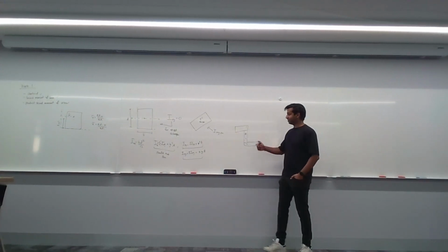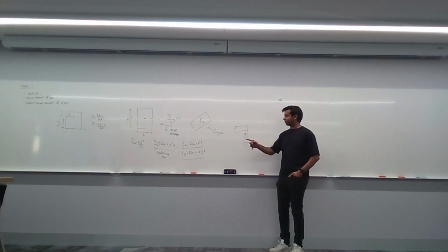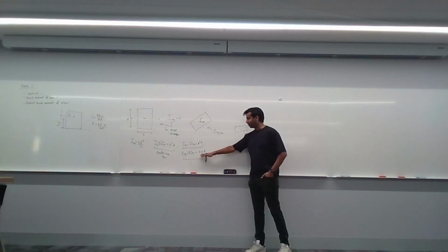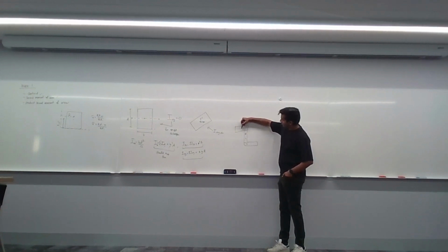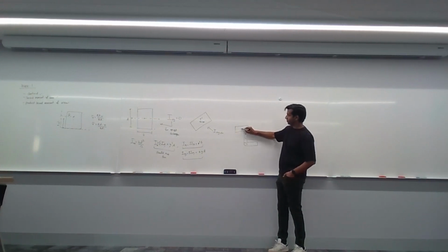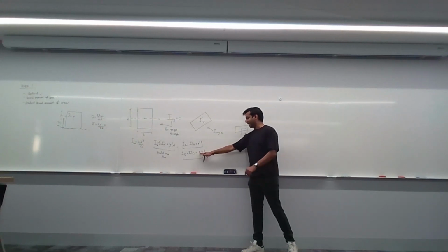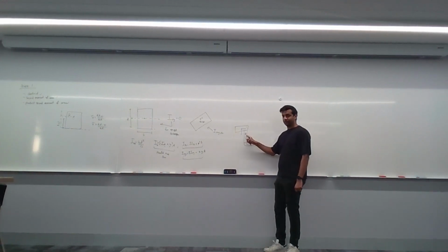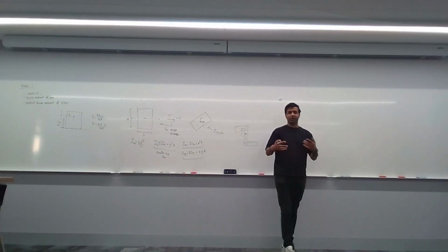Then we chuck this formula in to calculate the Ixy for the entire shape. So how would we do that? We first need to ask, what's the Ixy for all of the individual shapes? Because these are all upright triangles, it's all 0. So Ixy is 0, 0, and 0 here, so this entire term goes to 0. Now I want to calculate what xyA is for each term. For shape number 1, x is this distance from the centroid to this shape, and y is the y distance from the centroid to this shape. That's for shape number 1. So your first term will be xyA for shape 1, plus you do the same thing, xyA for shape 2, xyA for shape 3, and that's your product second moment of area. So that's how you calculate the product second moment of area.